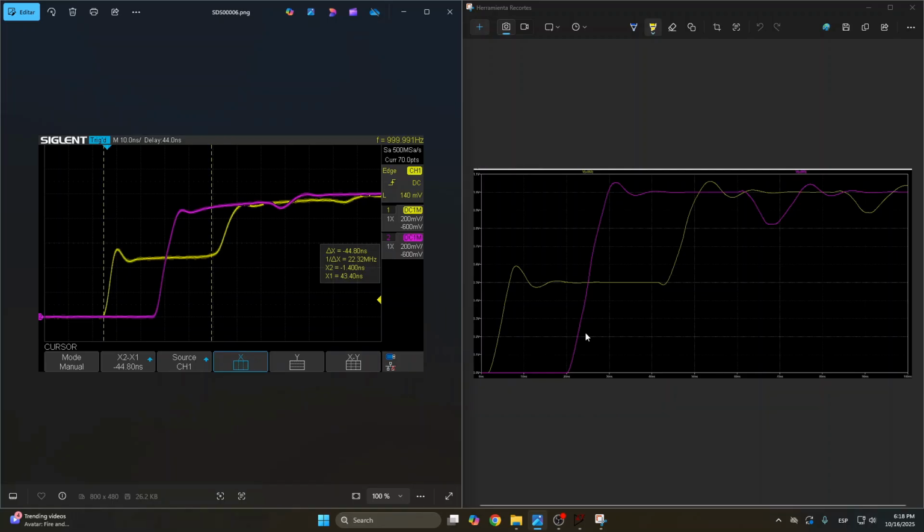And interestingly, after modifying the simulation to account for those extra transmission lines and the resistor and capacitor that are in the real inputs of the oscilloscope channels, we can see some similarities. Actually, the trace now looks a lot more similar to what we obtained from the oscilloscope. So, for example, this first overshoot on the yellow signal is almost identical to what we obtained from the simulation.